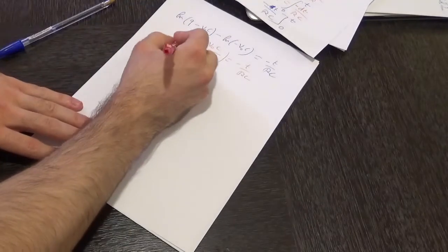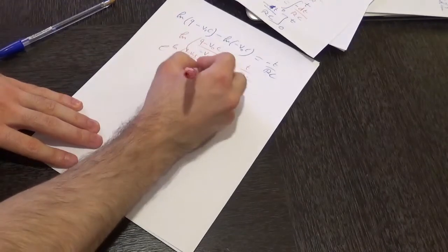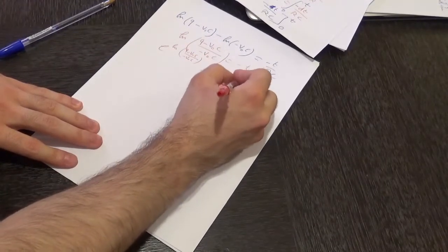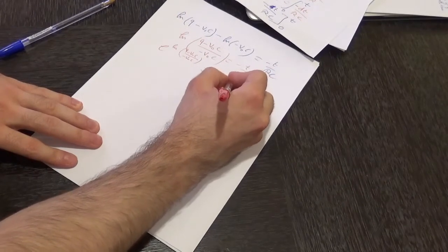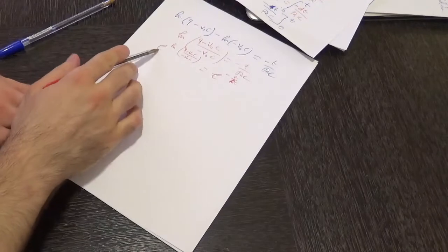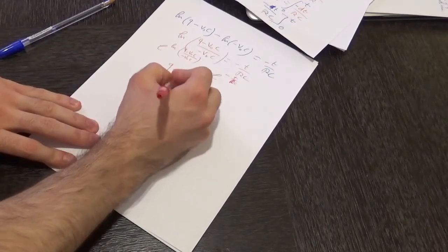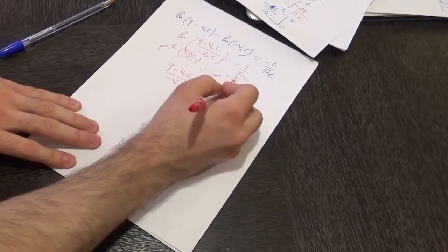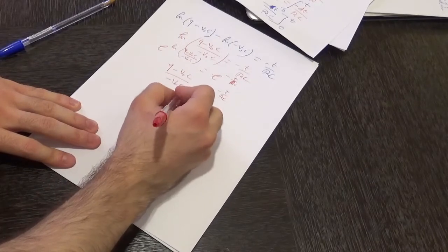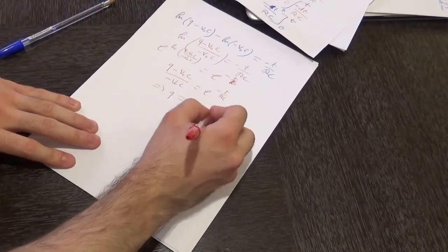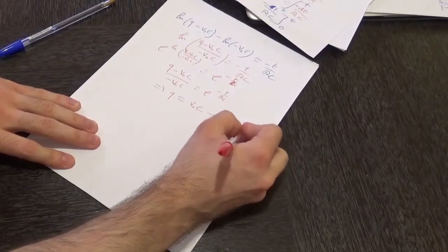So here we have the exponential of that ln, q minus v0c over negative v0c, equal to the exponential of minus t over rc, which we can replace with tau, or let's keep it rc for now. So the first exponential is going to yield q minus v0c over negative v0c equal to exponential minus t over rc, and over here we have now q equal to v0c minus v0c times exponential minus t over rc.